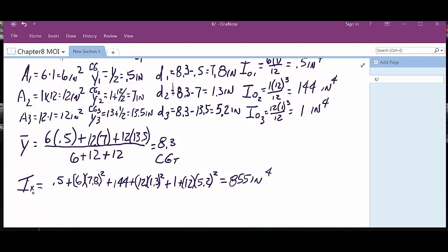You'd use the same type of numbers, but it would be different numbers because it's the height times base cubed divided by 12 instead. So it wouldn't be the same numbers. Wouldn't be that easy. Wouldn't it be nice? I guess if it was square, it would be, wouldn't it? Some kind of square thing going on.